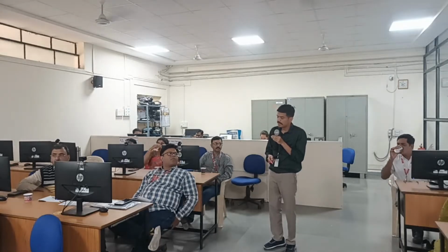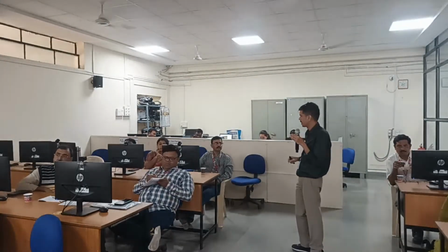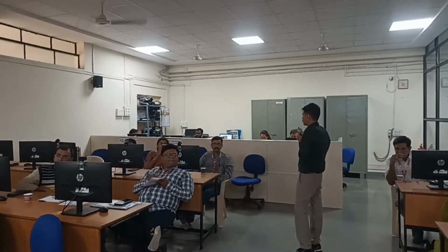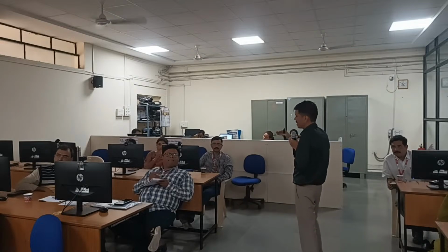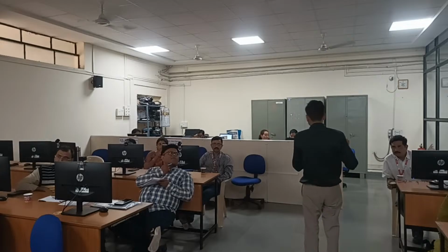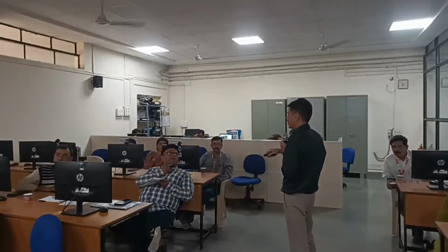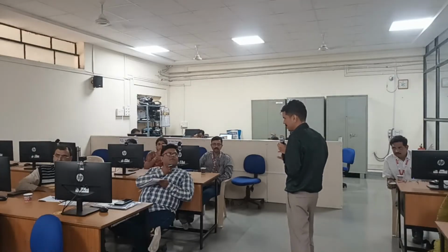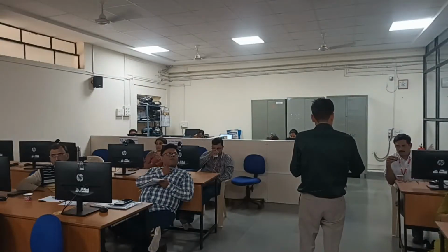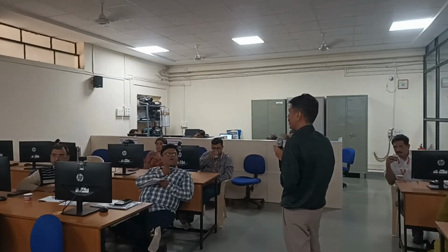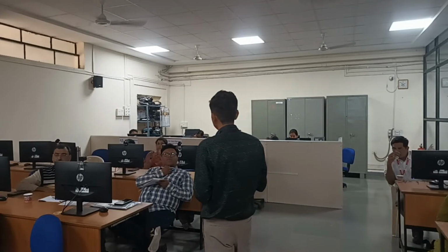The width and length will depend on the substrate you have asked for. Let us say you have a 10 nanohenry inductor and a 10 picofarad capacitor. How do you realize this on microstrip? You have to look at your stack up. What is the epsilon r? What is the dielectric thickness? What is the tan delta? What is the copper thickness and frequency? Based on that, 10 nanohenry will be converted to some length and width of a microstrip section. Similarly, the capacitor will be converted to some length and width of microstrip line specifically for that substrate. If you change the substrate, your length and width will vary, but the inductor and capacitor will be constant.